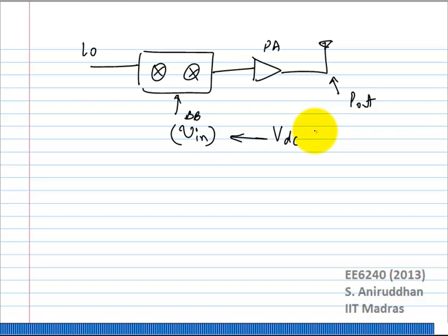Okay, I can choose to do this many ways. I can choose to give a real modulated signal. I can give a sinusoid, maybe of varying frequencies. I can give a DC also. But even if I give a DC input, because I have this up converter in there, which is mixing it with the LO, I will actually get a single tone signal.